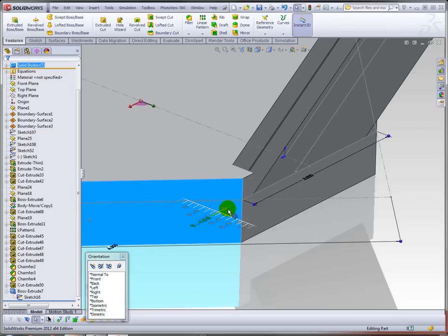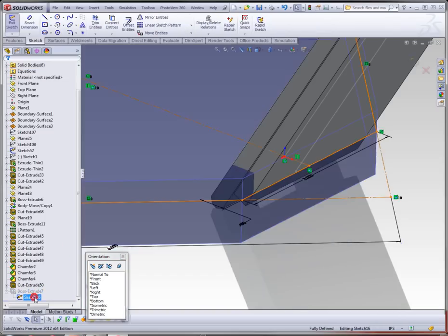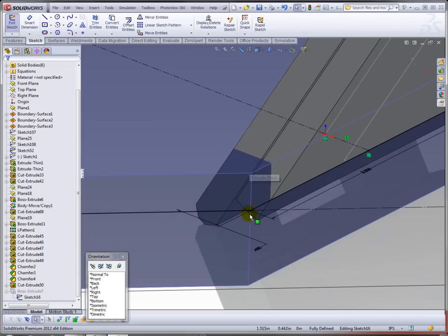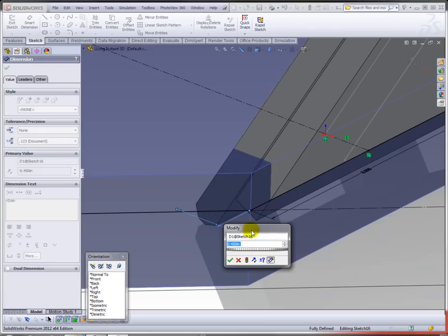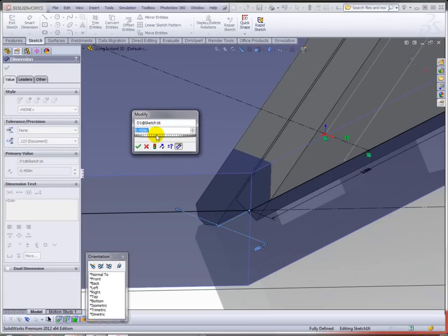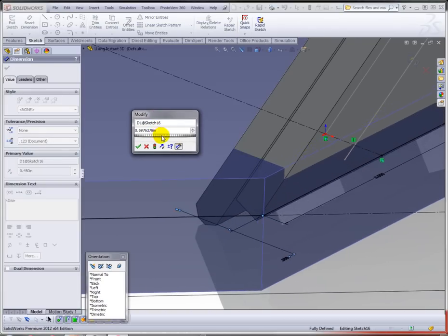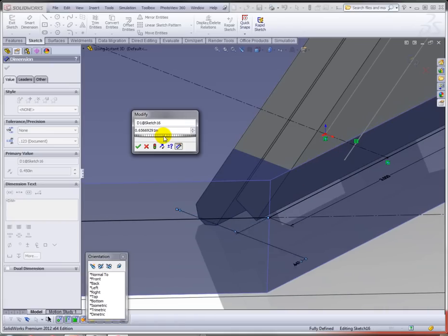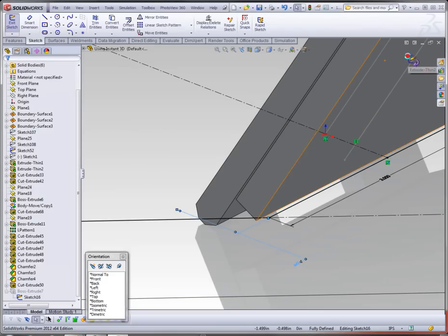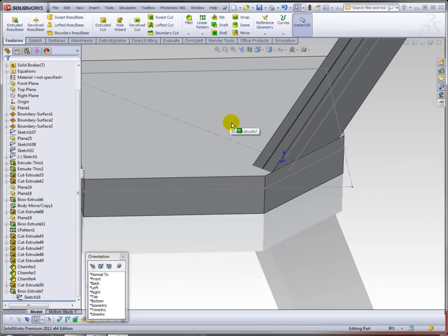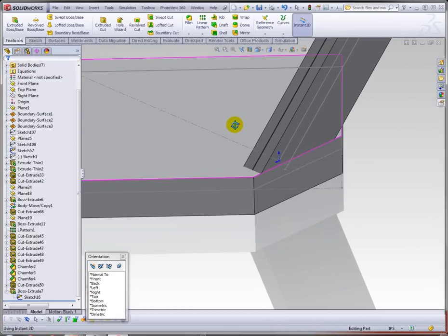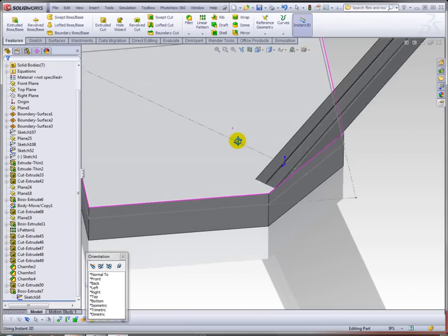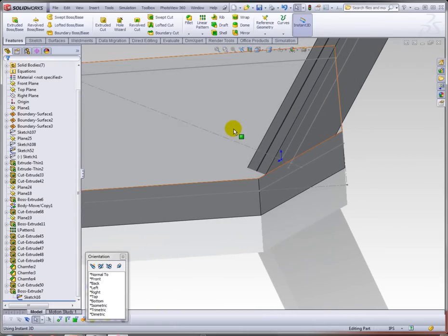So if I just go ahead and grow this out, let's just go into Sketch mode and do that, and then use my thumb wheel, holding down my Alt key to get a finer increment. Here I can actually just move and preview at the same time. While I make sketch changes, I can actually preview my model to get that very close to that back edge. And that's where Instant 3D becomes very handy. And you really should realize that it's a great helper, even when doing precise modeling where you can't normally visualize it without having that preview.